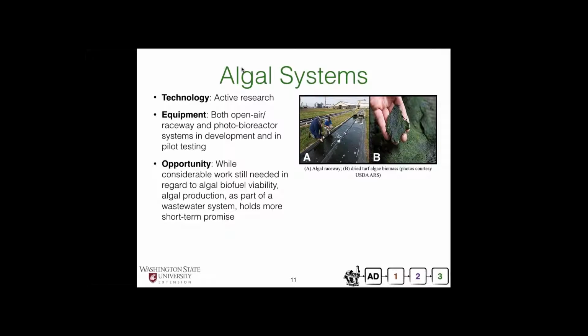We can do open raceways, which are essentially ponds or canals where we run the solid separated effluent, and we have seed reactors that we can use to grow up cultures of algae and then release them into these raceways to grow on the effluent.